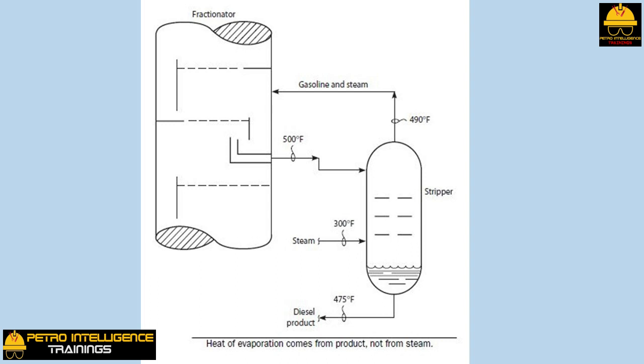If liquid drawn from a column is cooled below its bubble point as a result of ambient heat loss, we say it is subcooled. Mixing a small amount of steam with subcooled liquid will reduce the partial pressure of any vapor in contact with the liquid, but not enough to promote boiling. Eventually, as more and more steam is mixed with a subcooled liquid, it will begin to boil. But for a given amount of steam, the amount of vapor that can be boiled out of a liquid will always be less if the liquid is subcooled.